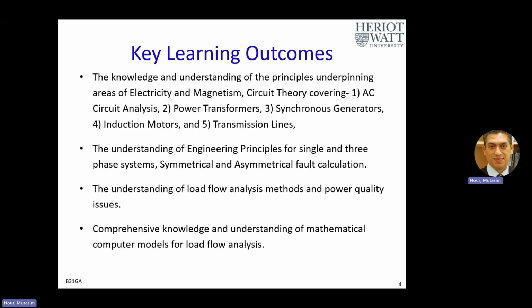Why? When there is a fault, the circuit breaker will trip and open the circuit. So we are protecting our system. The circuit breaker will take care, will open the circuit, and no current will be flowing. So the idea of all fault calculation is just to find the size of our protecting systems, which includes the circuit breakers, relays, switchgear, and fuses. Normally, these are what we use across the power system.